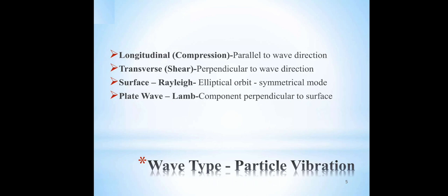Surface or Rayleigh wave. Surface waves can be used to detect surface breaking cracks in a test piece. Surface waves, also known as Rayleigh waves, represent an oscillating motion that travels along the surface of a test piece to a depth of one wavelength.